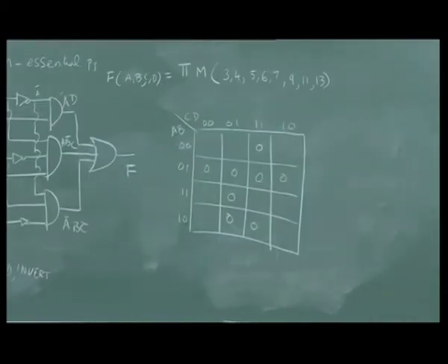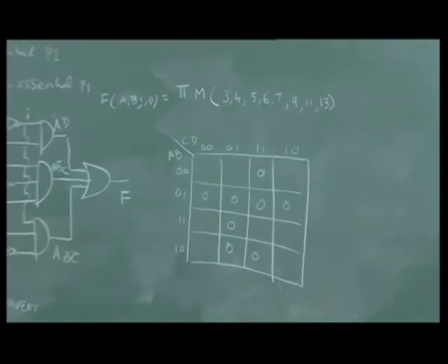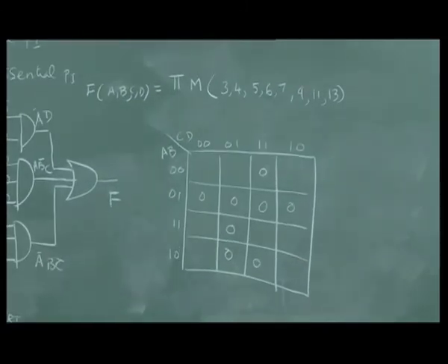Now I have used max terms, so I will tell you where are the zeros instead of ones. You map zeros, you have 2 choices: using zeros and directly get the expression, or use ones, wherever there is no zero, use a min term expression.